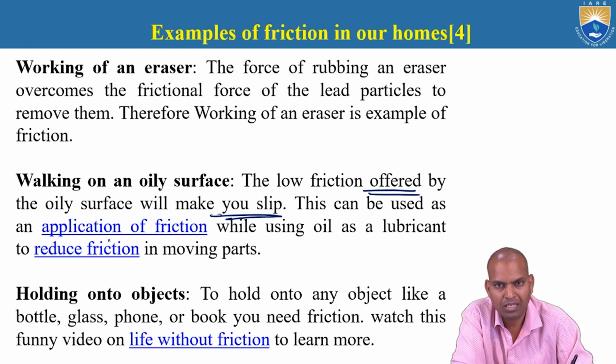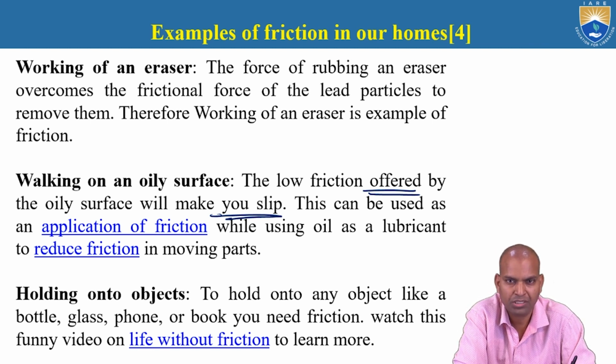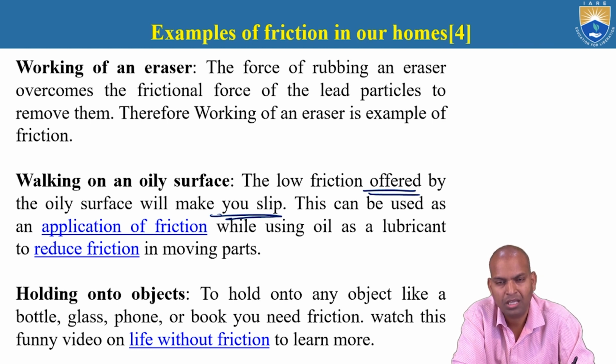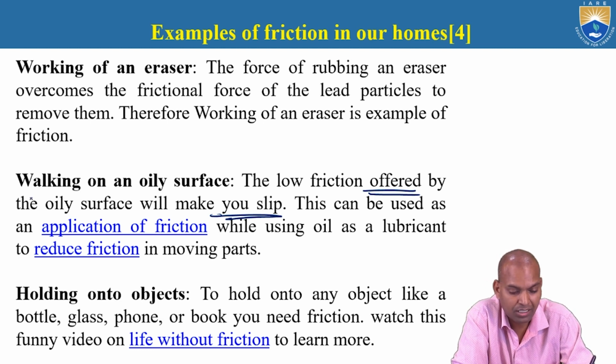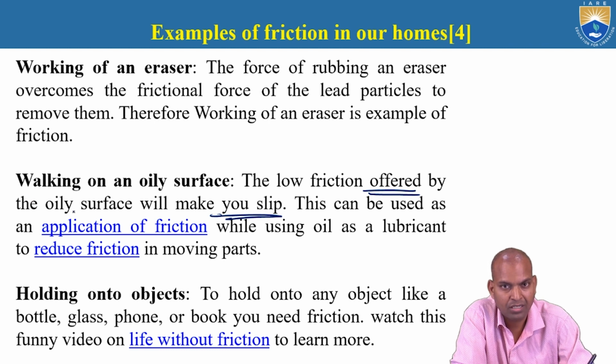The lubrication oil makes the two components rotate smoothly, reduces the heat generation and also reduces the friction. Reducing the friction reduces the heat generation, and thus reduces the damage to those two components. That's very important here. That's why lubricating oil is very important between two rotating parts.